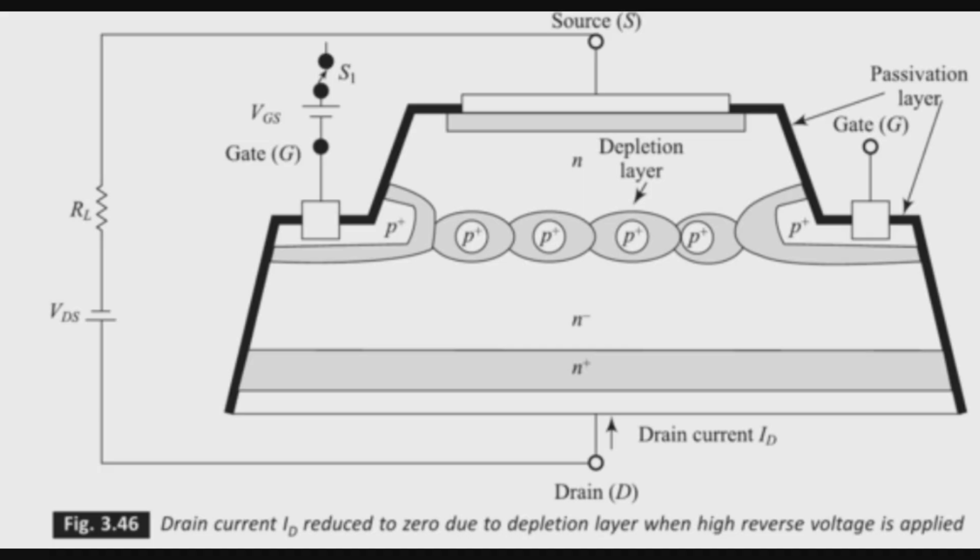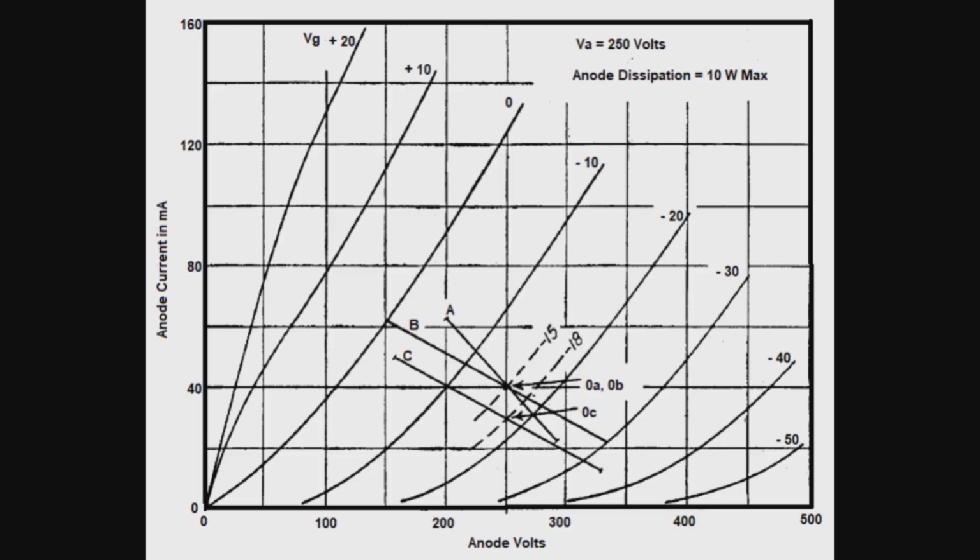This also explains why the conduction curves of a SIT closely resemble those of a JFET, just over a much wider voltage and current range. Both behave in a triode-like manner. Both provide continuous regulation, and neither is a switching device. Here, however, we reach an important difference.